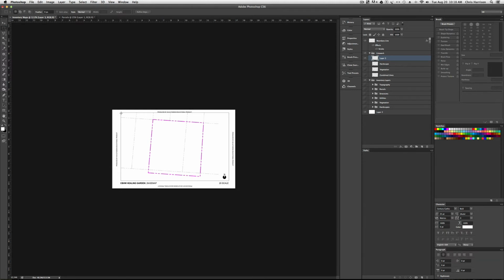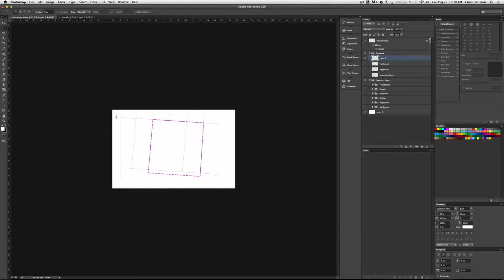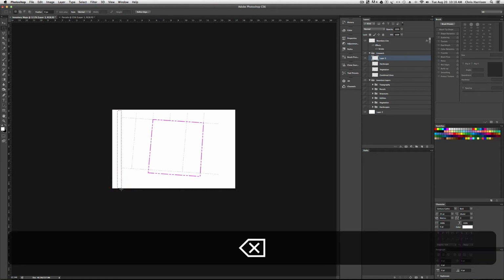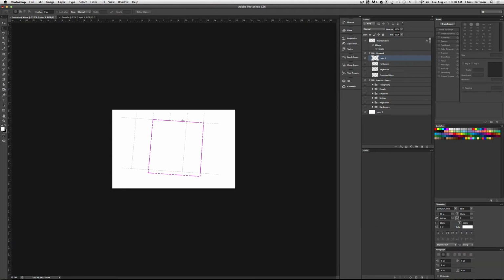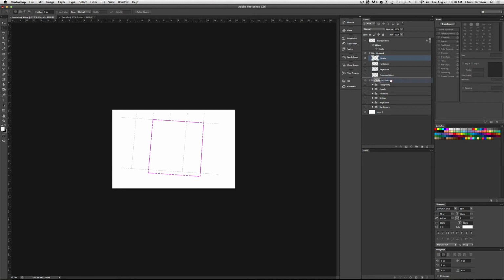Now for the parcels and the contours, I'm not going to Control Shift I. I'm not going to kill that to change the color of them. I'm going to keep them just black. Those are parcels, and I'm going to put that in the parcels layer. So when I pop that on, hopefully we'll see it. Parcels legend there. And topography, same thing. So we can kind of see what's going on with the site.